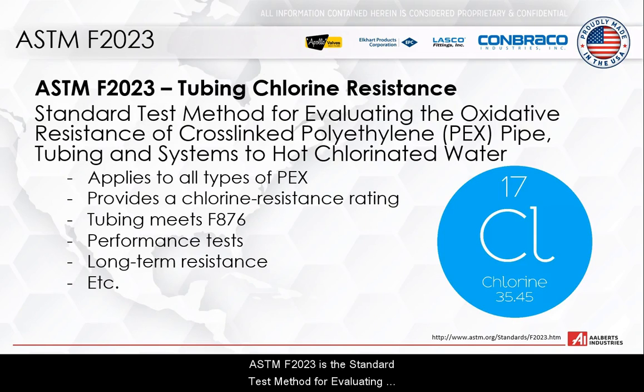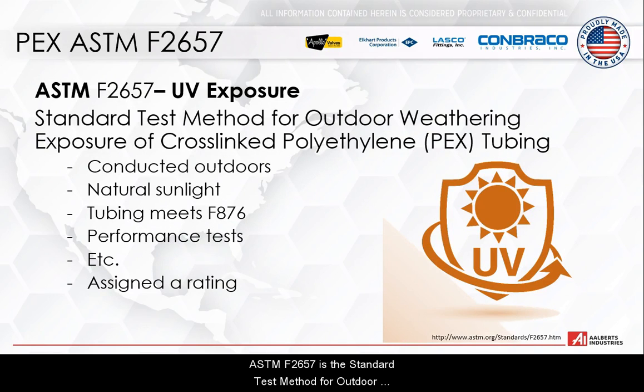ASTM F2023 is the standard test method for evaluating the oxidative resistance of PEX pipe, tubing, and systems to hot, chlorinated water. The tubing is assigned a rating that appears on the print line in conjunction with the next standard. ASTM F2657 is the standard test method for outdoor weathering exposure of PEX tubing and uses natural sunlight for UV exposure over time. It is important to stress that all PEX tubing should be kept out of direct sunlight. Always follow proper storage and handling instructions. Next, we'll discuss how the UV and chlorine ratings are listed on the product.